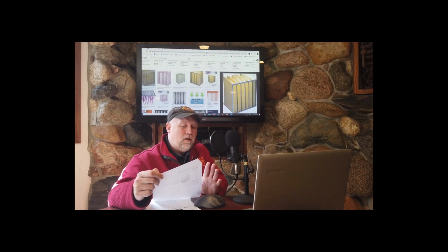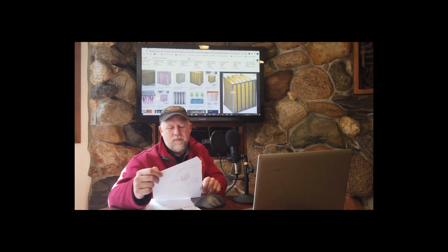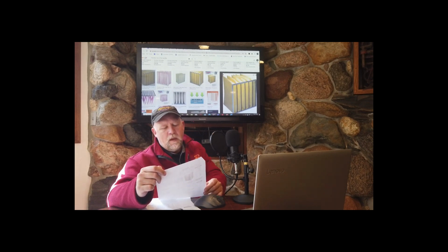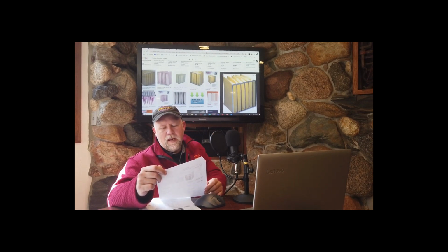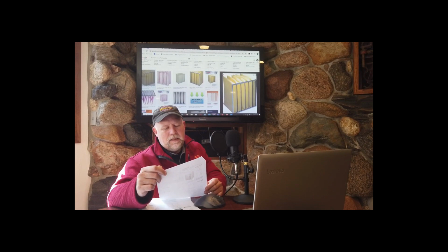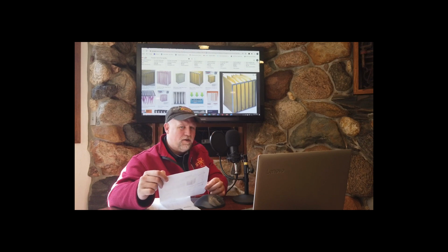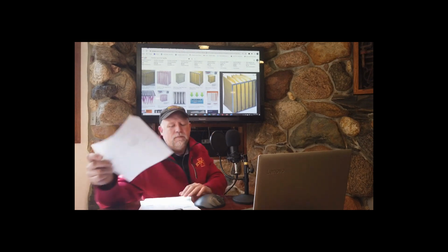A really, really good commercial one, maybe low end for a hospital or something along those lines. For 8 12-inch by 12-inch filters, and the 12 by 12, that's the face area, right? For 8 of them, it's $24. So now that we're at $3 a square foot of filter, obviously quite a bit more expensive.